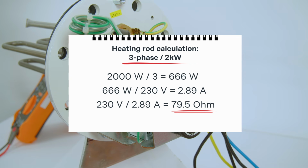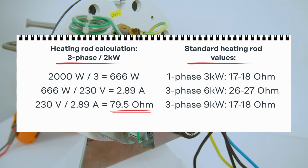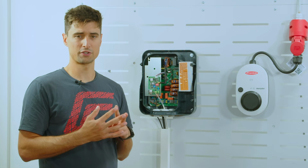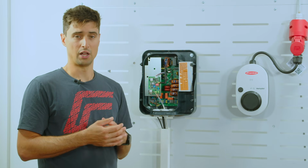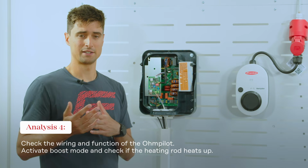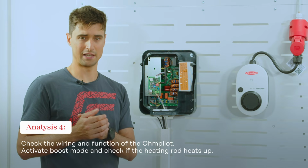So if it is a 1-phase 3 kilowatt heating rod, then you expect 17 to 18 ohm. If it is a 3-phase 6 kilowatt heating rod, then you expect 26 to 27 ohm. And if it is a 3-phase 9 kilowatt heating rod, then you expect again 17 to 18 ohm. We check the heating element and now only 2 sources for the error remain. On the one hand, the Ohmpilot itself, and on the other hand, the cabling between Ohmpilot and heating element.